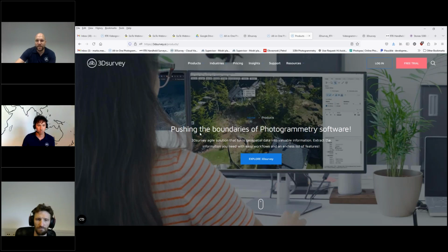But first you need to convert the raw scanner data into LAS or E57 format so that 3Dsurvey can open it. After that, you can do anything in 3Dsurvey that we have a feature for. The raw processing and point cloud generation you need to do in the scanner software, and then if you can export a point cloud, you can continue with no limitation in 3Dsurvey.